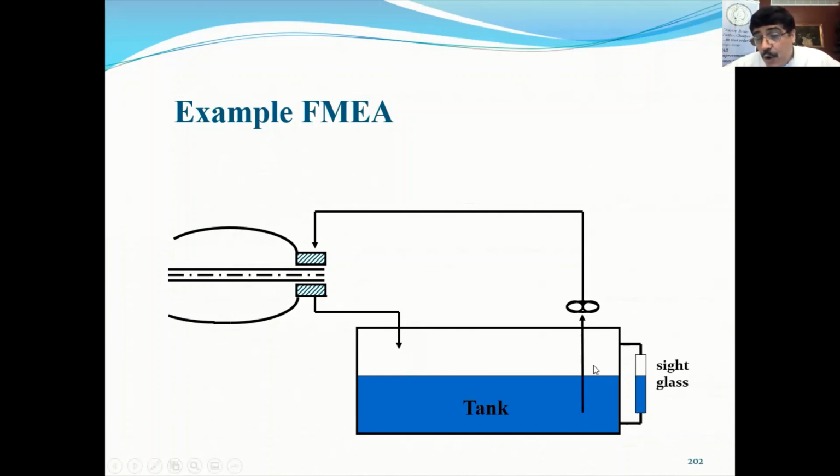The way to see how much oil level there is, there is something called the sight glass in the tank. Basically, a sight glass is an open pipe, so whatever level is here, you will see it in the glass here. Now, there were a number of problems with the pump. It was tripping because of low pressure, because of low oil, and that created failure to our bearing, and some failures can be very expensive, of course.